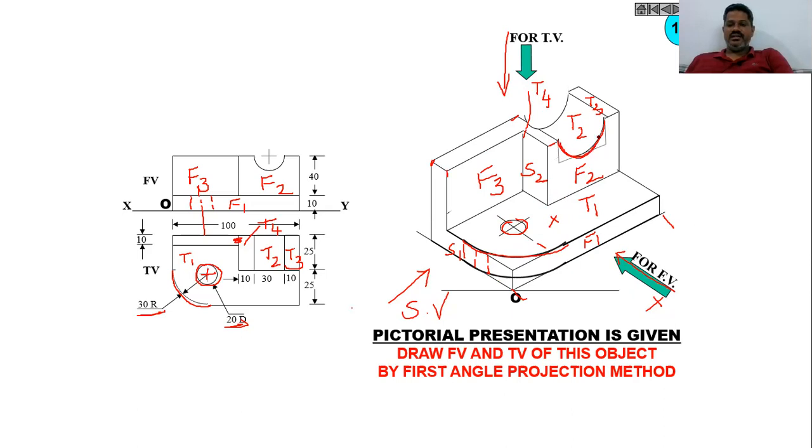Similarly, we have a cylindrical hollowness, a depression, here. We cannot see this depression, so we need to represent this depression also as a dotted line with the radius of this cylindrical depression. Now let me draw this first. With the given width, the width is 50 here, that you can see. With 50, draw a rectangle, then to the left side with a thickness of 10 and draw, and we don't get this line. Exactly an L shape we will get with 10 mm thickness.